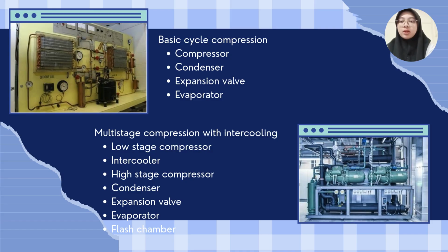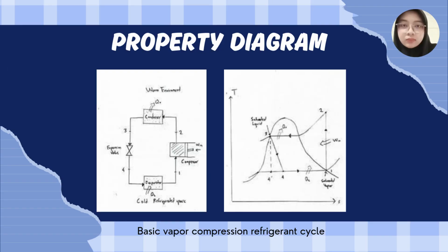Expansion valve 1: the liquid refrigerant may be partially expanded through a valve into a flash chamber to separate vapor and liquid phases. Expansion valve 2: only the subcooled liquid portion proceeds to the evaporator after final expansion, maximizing cooling effect. Cycle repeat: the low pressure refrigerant returns to the evaporator.